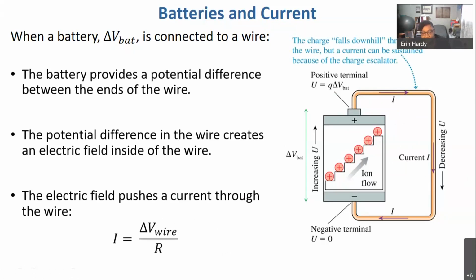Just as the light bulb in my hypothetical scenario a moment ago ultimately takes potential energy away from a charge carrier at a fairly rapid rate, exactly the same thing is happening inside the wire itself. So if I could take a voltmeter and put it not directly on the positive or negative terminals, but, let's say, 1 millimeter above and below each of those, I would be measuring the potential difference for the wire itself. And that delta V for the wire should be the same as delta V for the battery. So this gives me two different ways that I can think about the current that is present in this circuit.